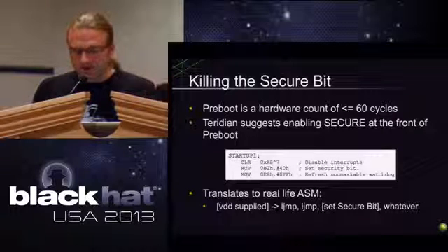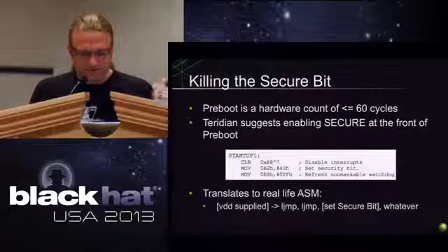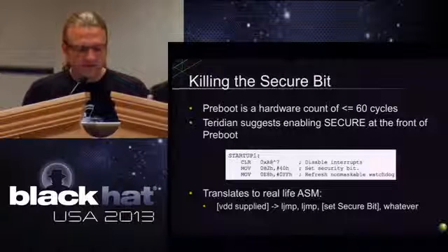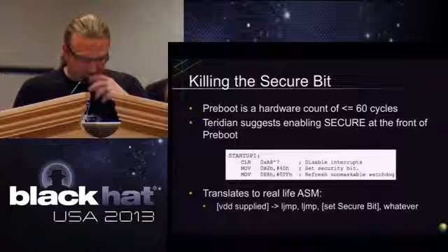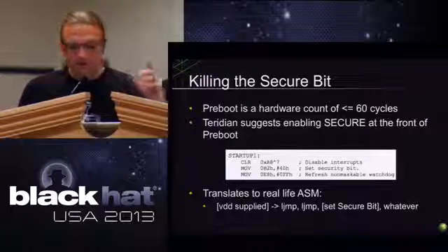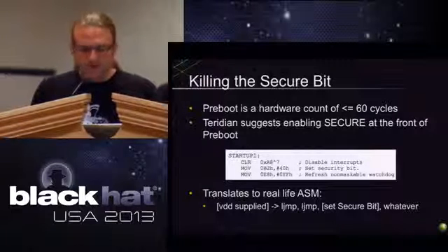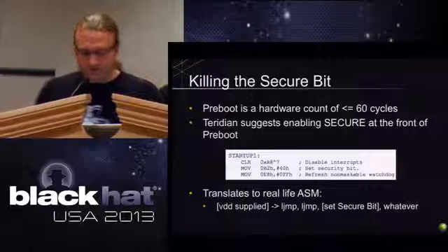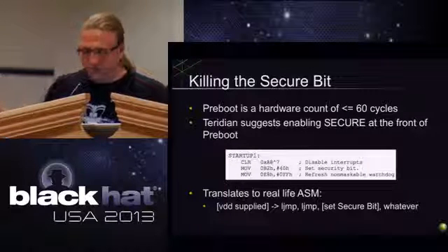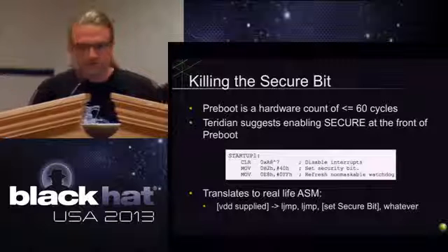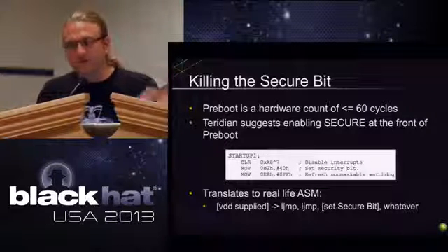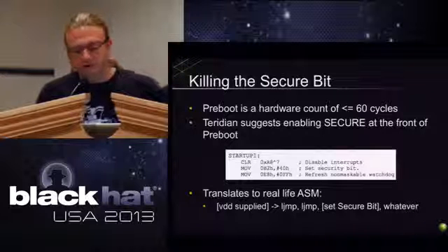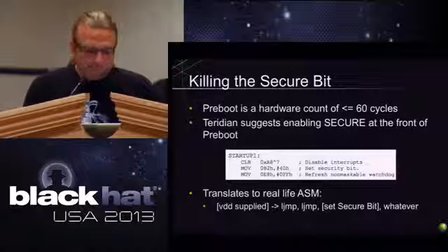When you start looking at all of the Teridian documentation, which is just massively fabulous, it covers everything in the world you would ever want to know as a developer. They give you the demo code to turn that up, and they tell you exactly where to put it. They say the very first thing you should do is this is what your code looks like. If you do this, security will be set, and you can't debug the thing after it gets out of pre-boot. It'll never actually go into ICE.